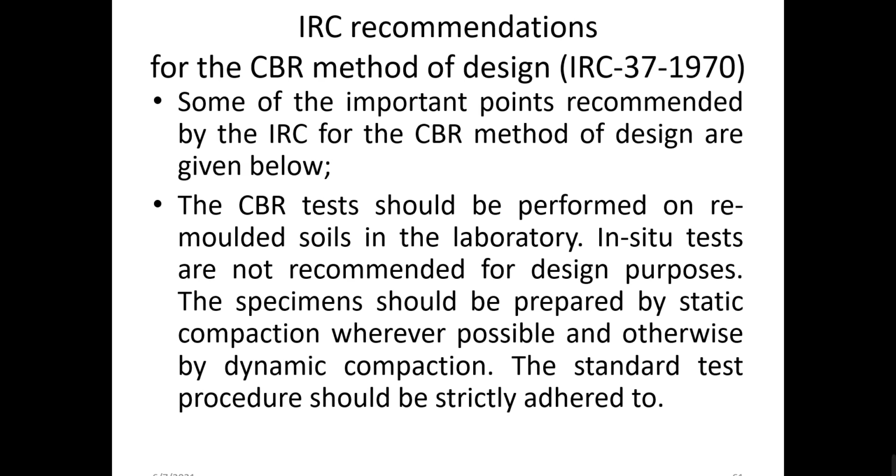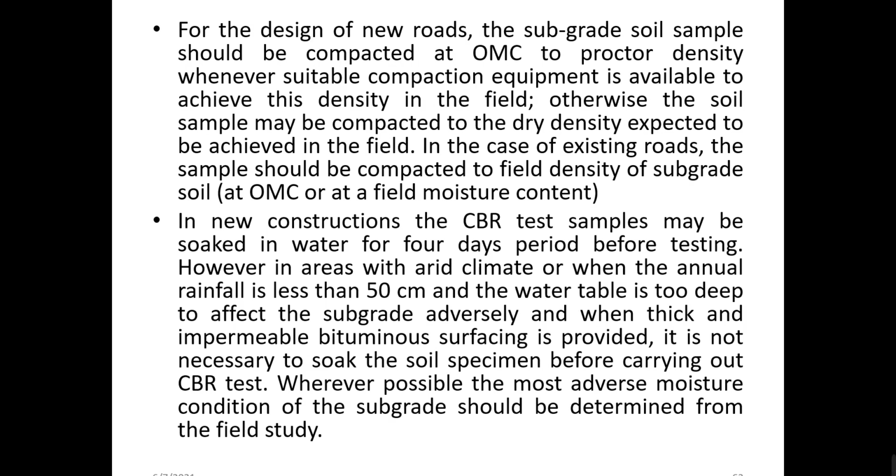And also, for the design of new roads, the subgrade soil sample should be compacted at the OMC. They have given the test procedure for how to conduct the CBR test as per the guidelines. You know that usually there is a practice of collecting the soil. The CBR of that particular soil should be tested at the OMC. At the desired OMC, we are going to obtain the maximum dry density.